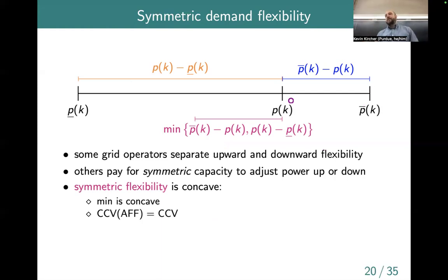So every day, maybe between noon and 4 p.m., something like that, the grid operator would run a big optimization, and they say, okay, everybody tell me how much power you can produce or how much you're going to need to consume or how much flexibility you have if you're a battery or something like that. They put it all together and they solve a big optimization problem looking ahead over a one-day horizon.